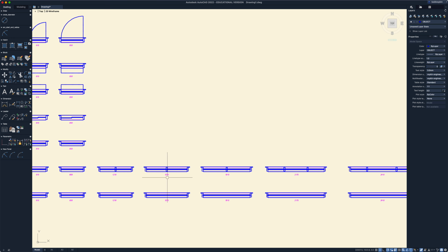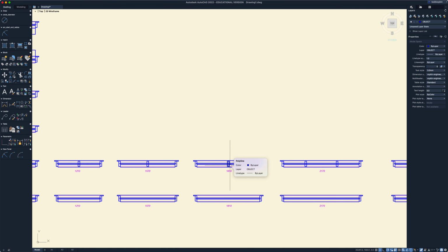And we need this separation in the window right here. We need another part of the frame providing support down the middle of the window, and it also reduces the size of the glass that's moving. If that happened to be like 1.8 meters wide, that would be nearly impossible for somebody to open. It'd just be too heavy and a little bit too dangerous as well, with chances of breaking it or somebody hurting themselves because of the sheer weight of it.